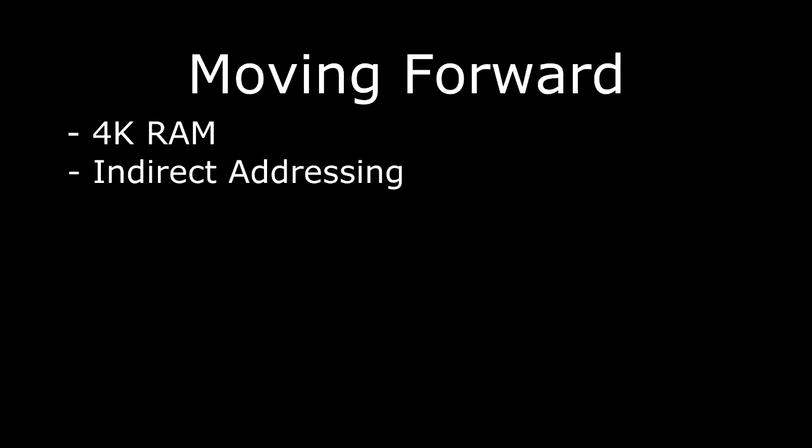Okay, so moving forward now, we'd like to have a full 4K of RAM, 12 bits of addressing. We'll have to figure out how to address that, since in the original design there were 4 bits of opcode and then 8 bits of address on most of the instructions. So that's going to require some indirect addressing. We'll get into that. And then we have the question of how to implement it.